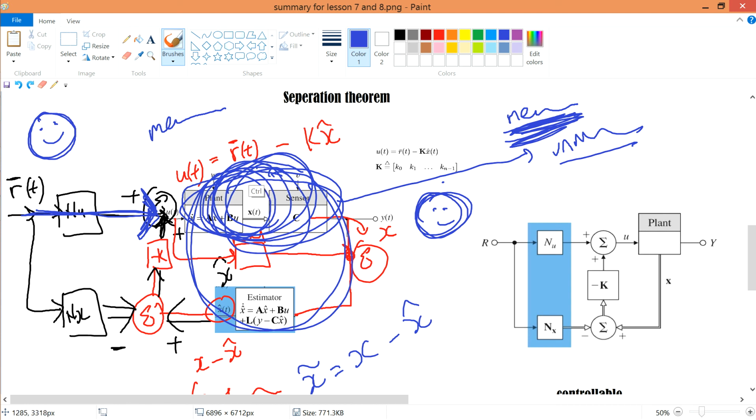So therefore the key issue is that you want to have an observable system to give you measurable data, so that you can use the measurable data to control things with reference to your reference signal. Your reference signal cannot change anything, but your observable system can, and the controller and the feedback, your minus K and your minus L, if you still remember, are the things that you would use to help you control your observable system.